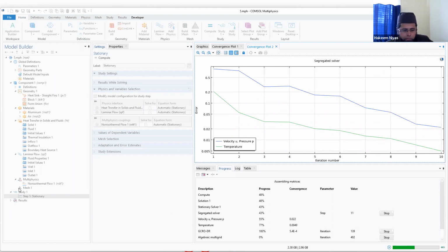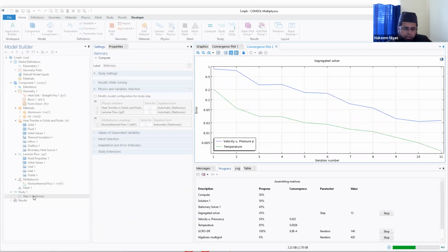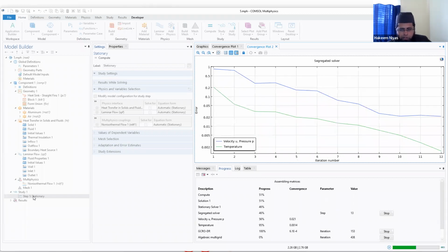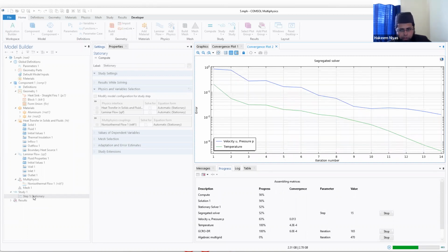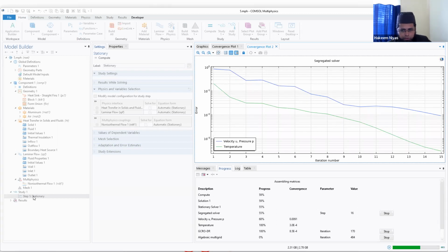So, and one more thing, solver part also I haven't touched much, but solvers is a very important thing which needs more fine tuning when it comes to highly nonlinear problems. So there are different solvers available, and COMSOL by default chooses the best solver. That is a good thing with COMSOL when compared with other software. So whatever things are there, the mesh, we have physics controlled and we have user controlled available. And similarly, we have multiple options available in front of us in COMSOL to choose.